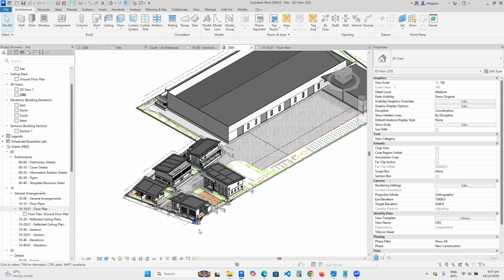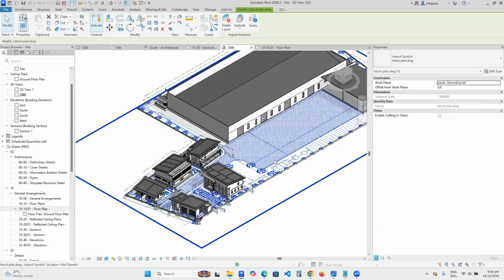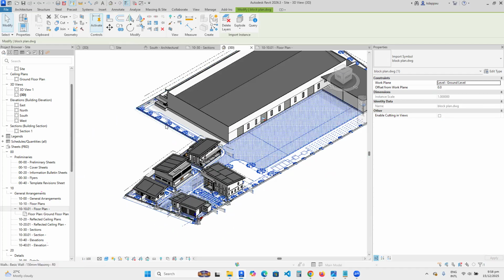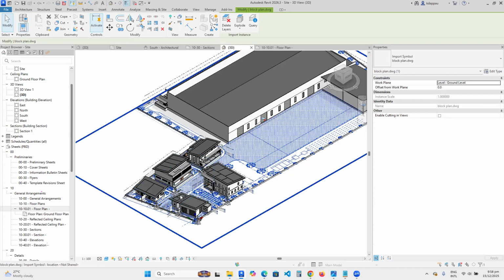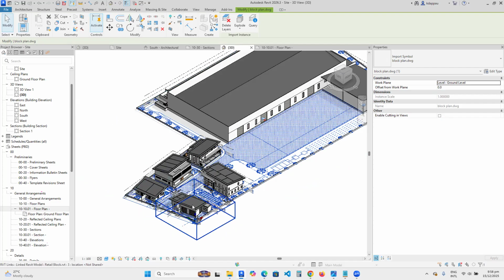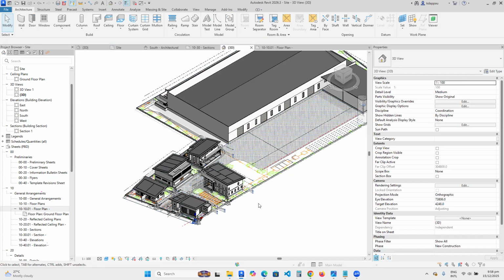Anytime you are linking the building, we have what we call shared coordinate system. So you can take the site and then give it a coordinate system. And then you bring in each of the buildings and then place the buildings. And then the buildings will share the coordinate system of the world of the site. And there are tools in Revit that help you to do that.